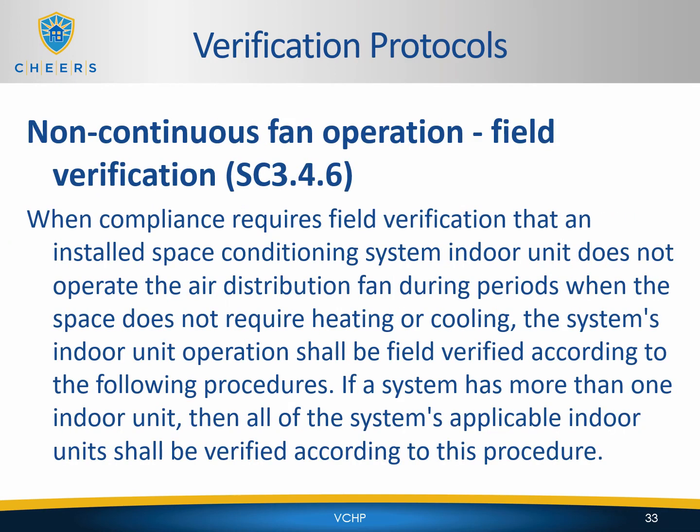Non-continuous fan operation field verification. This is found in section SC 346. When compliance requires field verification that an installed space conditioning system indoor unit does not operate the air distribution fan during periods when the space does not require heating or cooling, the system's indoor unit operation shall be field verified according to the following procedures.